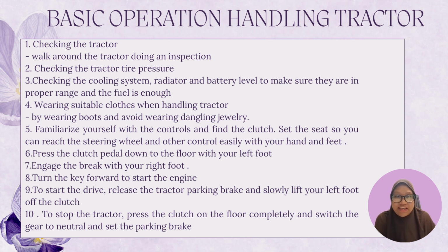The first thing is checking the tractor, walking around the tractor doing an inspection. Second is checking the tractor tire pressure. Third is checking the cooling system, radiator and battery level to make sure they are in proper range, and that the fuel is enough. Fourth is wearing suitable clothes when handling the tractor. Fifth, familiarize yourself with the controls and find the clutch. Set the seat so you can reach the steering wheel and other controls easily with your hands and feet.